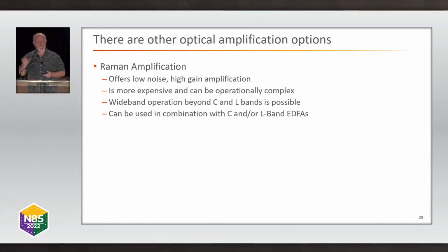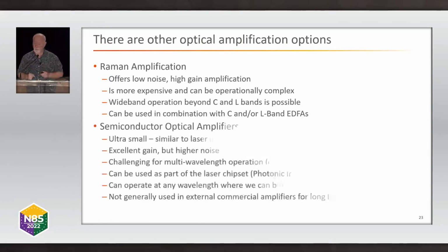The Raman pumps are very, very powerful, and they operate in the infrared. So it can be shining into your eye. You don't know it because it's not visible, and it can be burning, damaging your eyesight. So there are lots of interesting operational factors with Raman. But it can be used for wideband amplification beyond the C and the L bands. And it can be used in combination with EDFAs. That's very common. It is commonly used today in long-haul networks as a hybrid Raman EDFA amplifier.